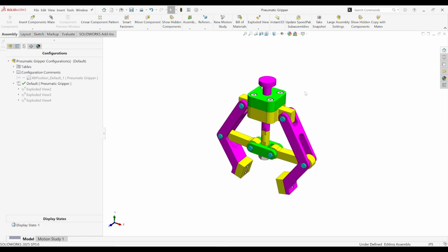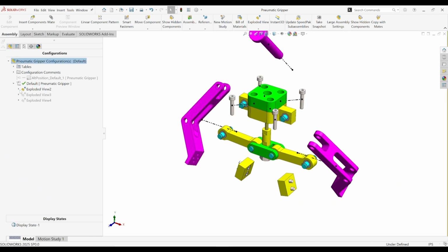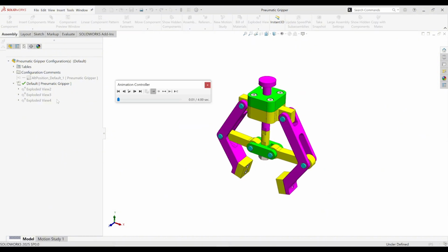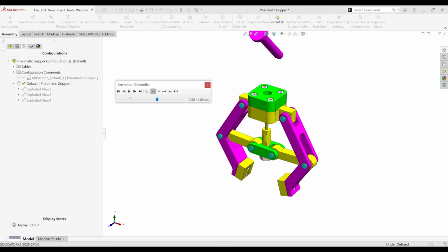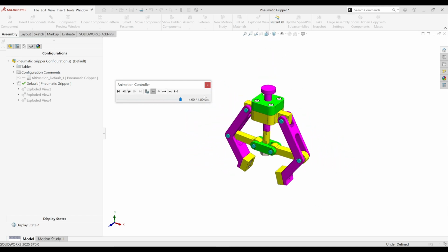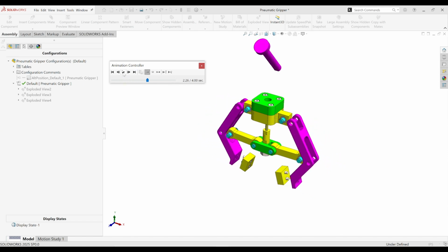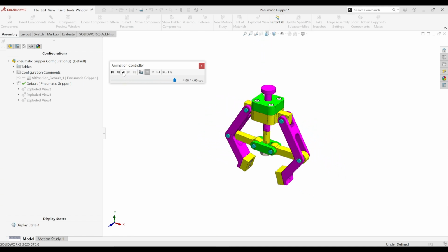To do that, we're still gonna use this guy, and I'll collapse this. So to animate, you right click on the explosion after having toggled it on or exploding it, and then you can select this animate collapse. So once you have that, you can see, I'll zoom out a bit. This slider comes up, or this playback menu comes up. So this is the play button. I'll replay it again, so you see how everything twists back.